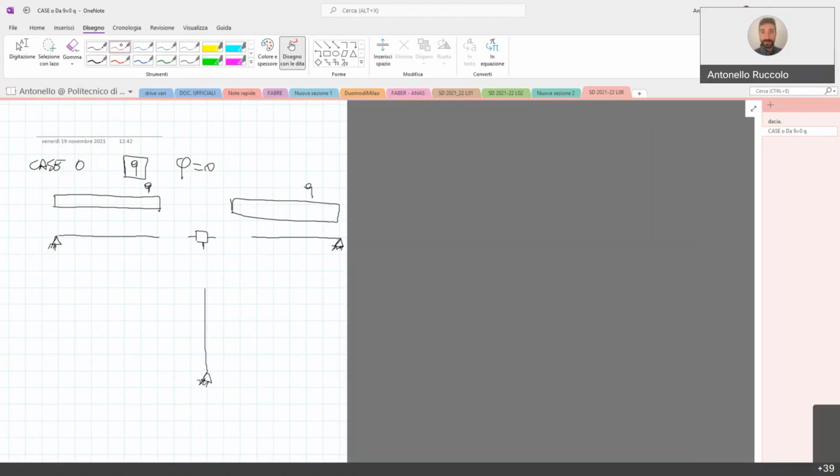can be applied or on the node or on the structure, but they are always the same. Well, so let's consider what is the effect of the load Q acting in the beam A on the node B. Okay, first of all, we draw the deformed shape. In the node B, it will be like this, because in the node A, sorry, in the beam A, it will be like this, because in the node A, we have the possibility to rotate. In the node B, we have that the rotation is prevented, because I am declaring it here.